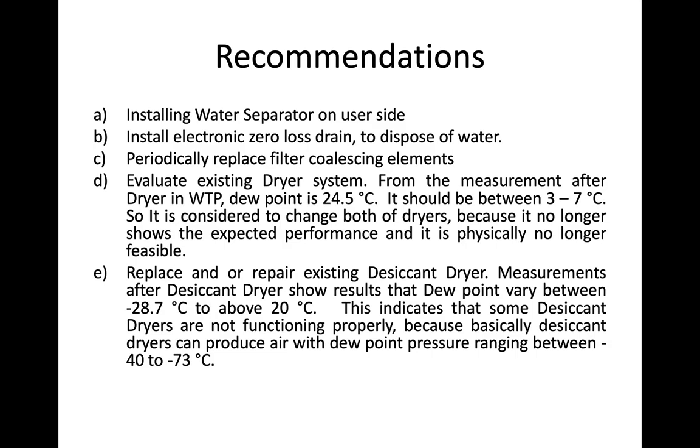And then the fourth recommendation, we suggest evaluating the existing dryer system. From the measurement after the dryer in the water treatment plant, dew point is 24.5 degrees Celsius. It should be between 3 up until 7 degrees Celsius.